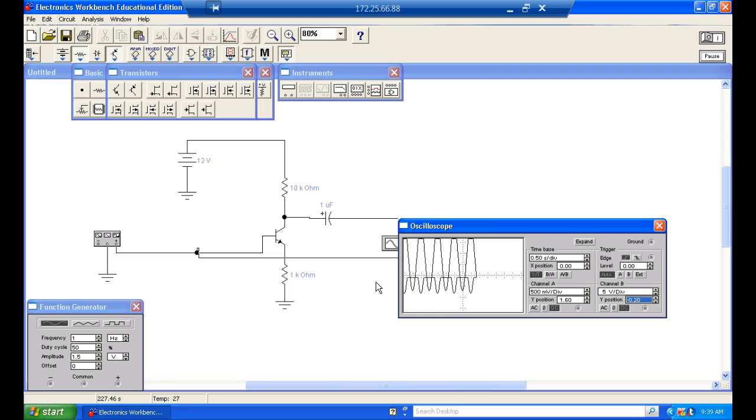Right? You understand that? Because if it was 180, I would not have that little space right there. Can y'all see that? And I would not have that little gap right there. It's hard to see, but let's see if I can set this at 0. Yeah. We can't see it, but there's a little space right there because it took 0.7 of a volt to turn it on. So what we'll do is let's bias it a little bit.